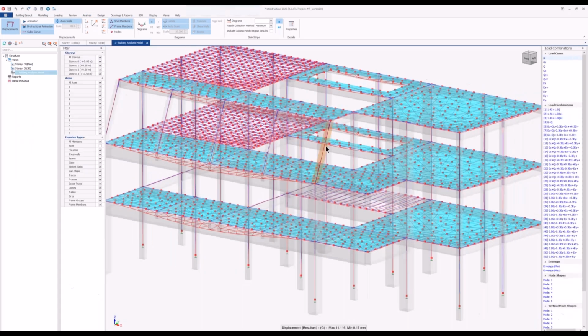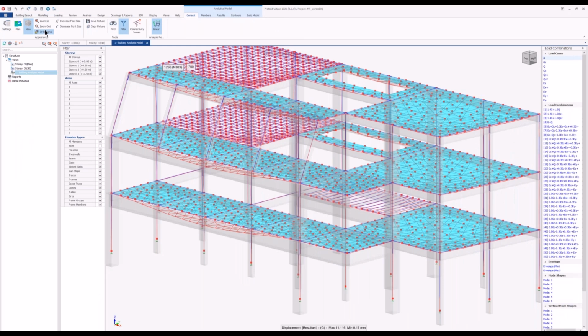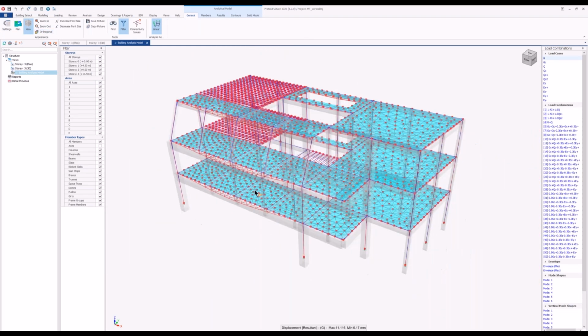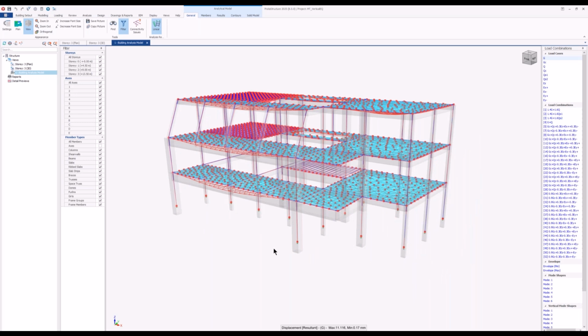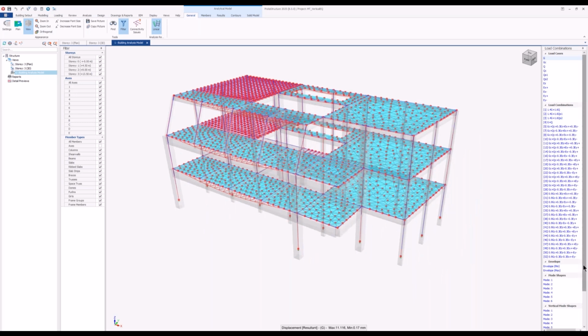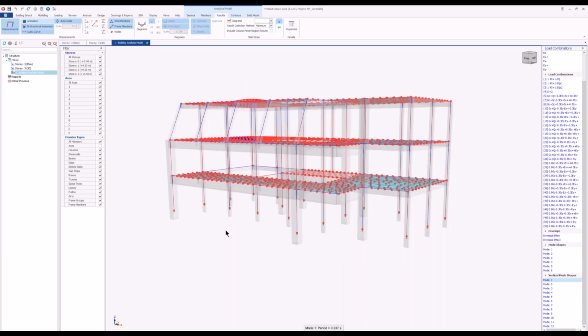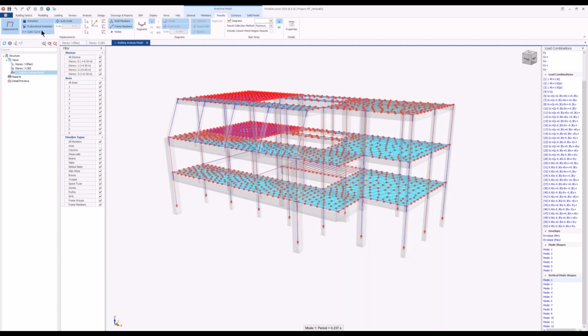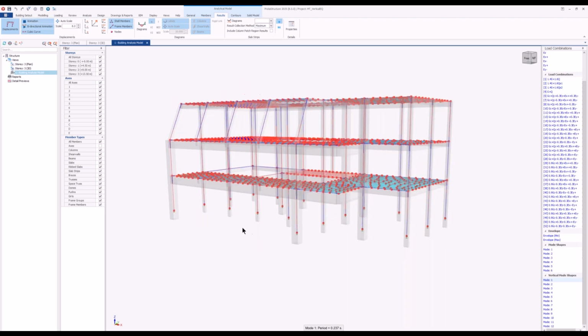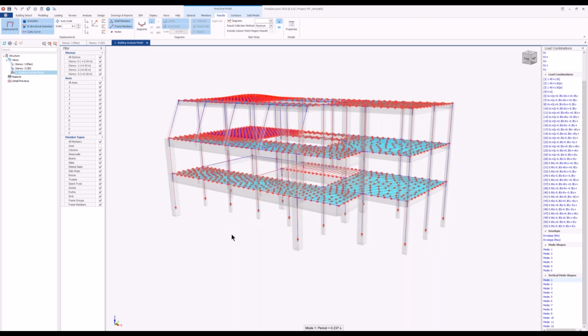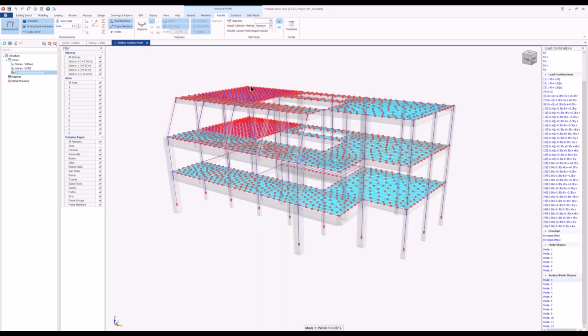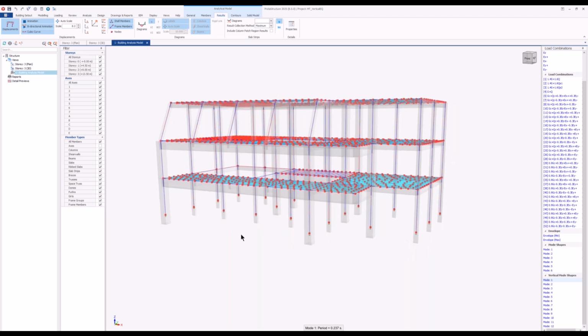Anyway, after you perform the analysis, you can check the analysis model. So this is the analysis model created for this project. First things first, we can just look at the mode shapes. Let's animate this. Maybe we can exaggerate the animation scale, like 8. See, in the first mode, only the large span waffle slab is vibrating very dominantly.